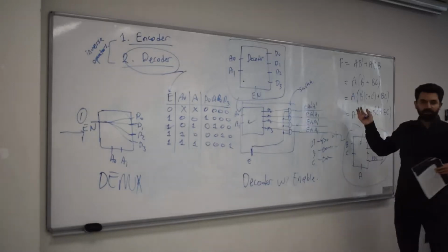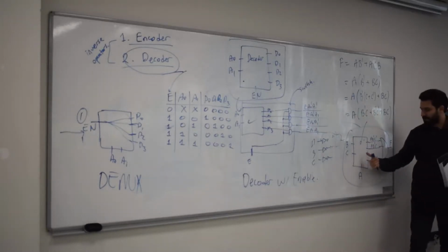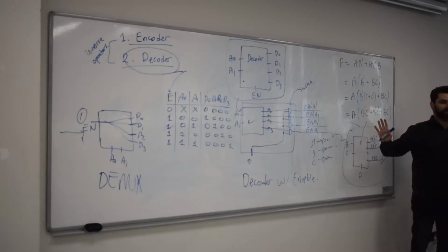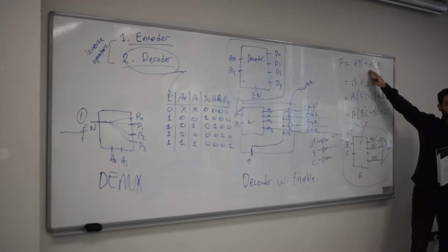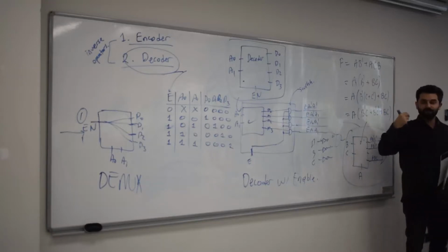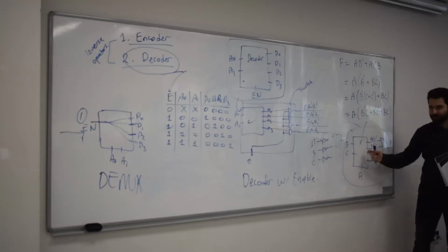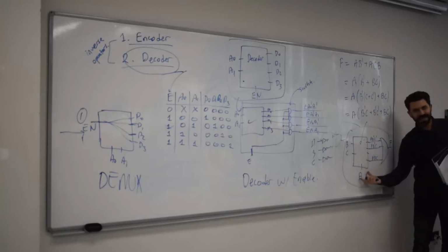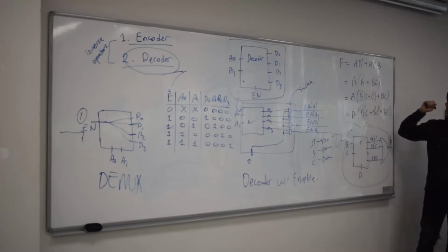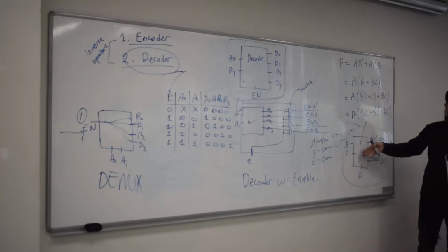And you know how to, for instance, if I didn't give you a decoder with an enable, okay, let's just use only decoders and they don't have any enable. Can you implement this function using a 2x4 decoder? Yes? No. Why? Because you've got 3 inputs and a 2x4 decoder has only 2 inputs. The reason that we're able to do that with this decoder is because there's an enable functionality that we can push the third input to, so that we can get this functionality. But if you've got no enable, then you cannot use this decoder.